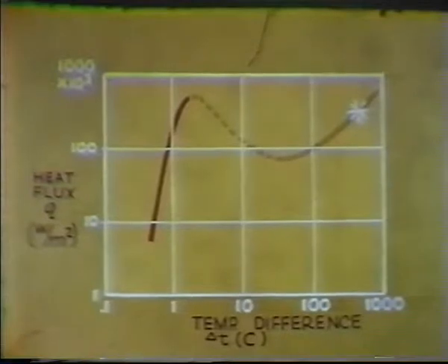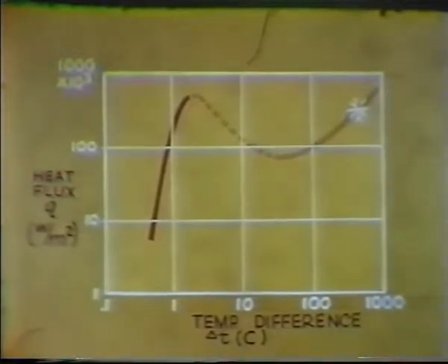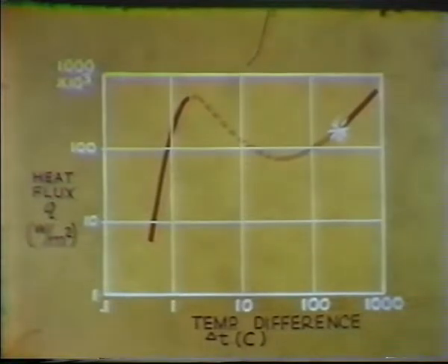Nucleate boiling from the wire is replaced by film boiling. In the present system, the current in the wire is controlled by a constant voltage source. Thus, the sudden increase in wire temperature and corresponding increase in wire resistance results in a slight drop in heat flux. Providing the wire temperature does not exceed its melting point, film boiling will continue as the heat flux from the wire is increased further. On decreasing the heat flux, the film boiling process does not retrace the original curve.